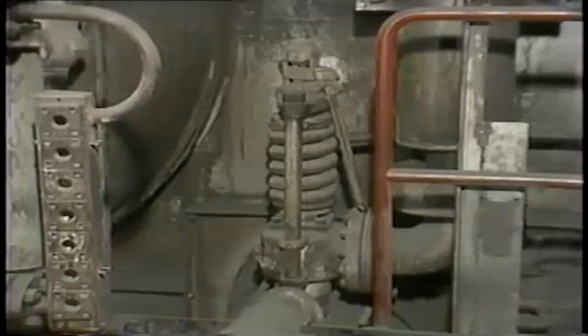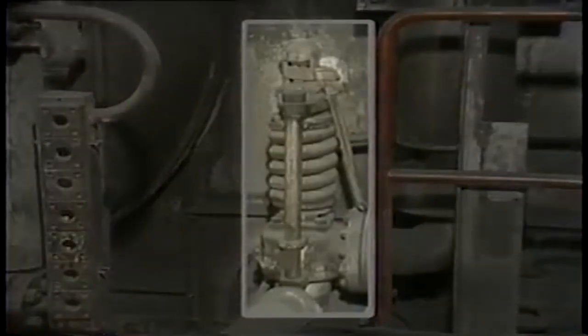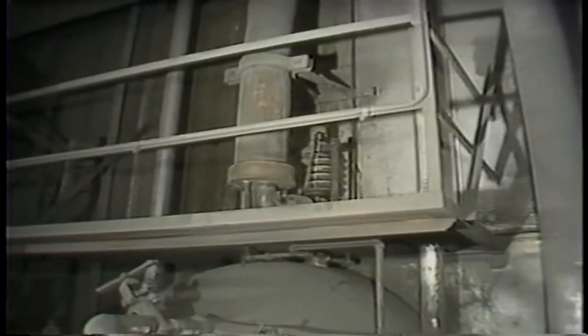To protect the boiler from overpressure, a special type of valve is installed in the superheater and reheater outlet lines and on the boiler drum on drum-type boilers. These special valves are called safety valves, and they protect the boiler from overpressure. Safety valves come in a number of shapes and sizes. Regardless of whether a safety valve is installed on a boiler drum or on a superheater or reheater, essentially, safety valves all work the same way.